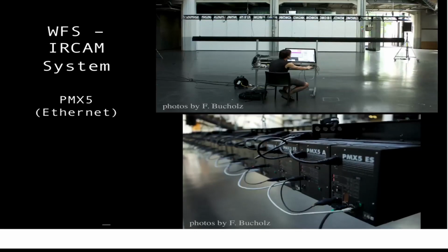To achieve a larger area for the audience, we used a larger line array based on the WFS system of IRCAM, which is built of Amadeus PMX5 units. These units are about 13 centimeters wide, extending the range of WFS reproduction to up to 4 kHz.